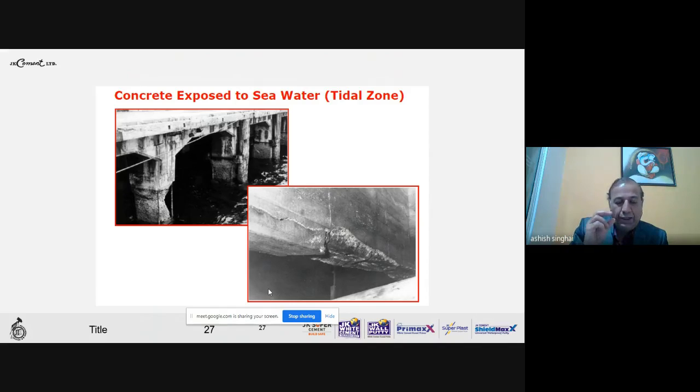Now, in this process, as the steel bar within the concrete expands, it exerts stresses on the surrounding concrete. Since concrete is a rigid member, when stresses are exerted within it, what will happen? A lot of cracks start opening up, and it also sets off a chain reaction.